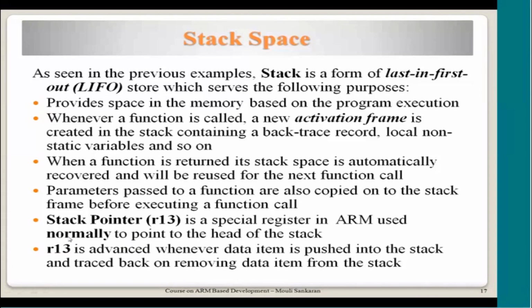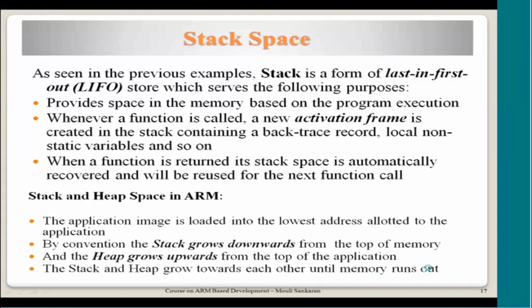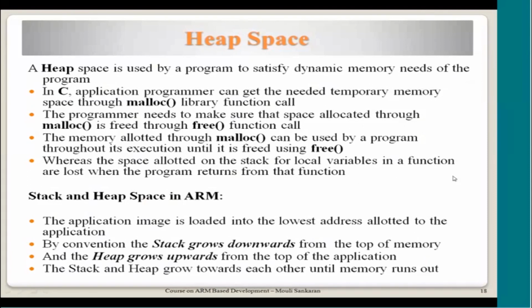And so R13 is used as the stack pointer here, and whenever a data item is pushed, R13 is incremented or decremented based on how the stack grows, and when the value is removed, R13 is adjusted back. Now we also have the heap. This is the data area.